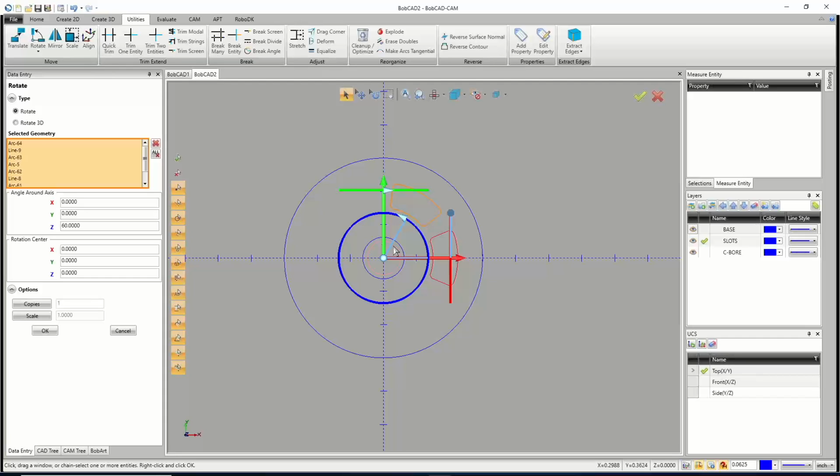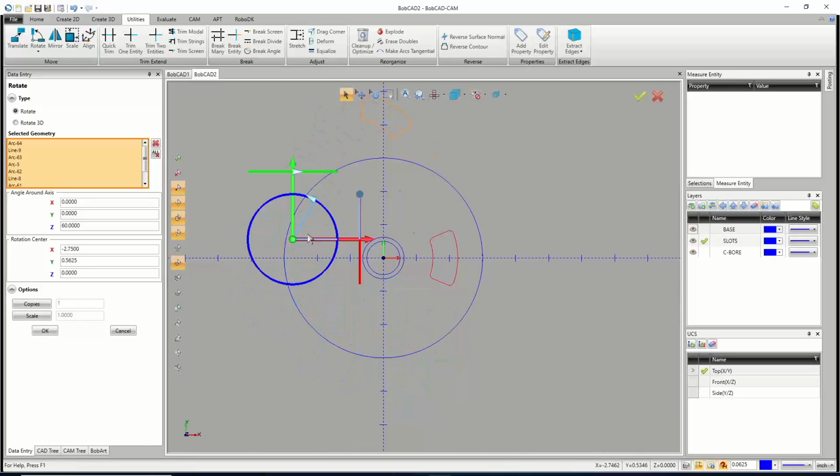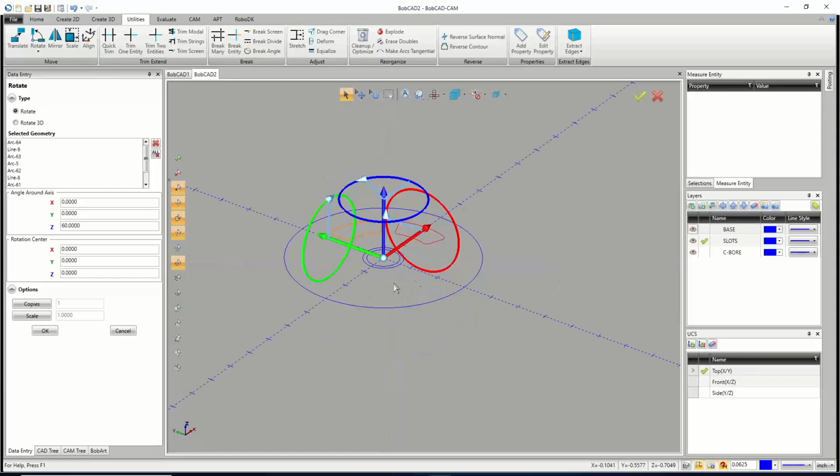So he didn't know that the rotation center was what you're rotating about. Just so happened for all his years of working, he worked right around XYZ 0. And this was one of the first parts he ever imported and worked on. It was shocking. So the rotation center is the point in which you're rotating about the geometry.